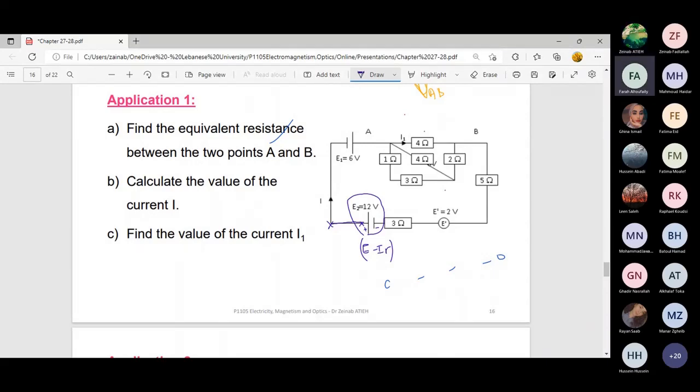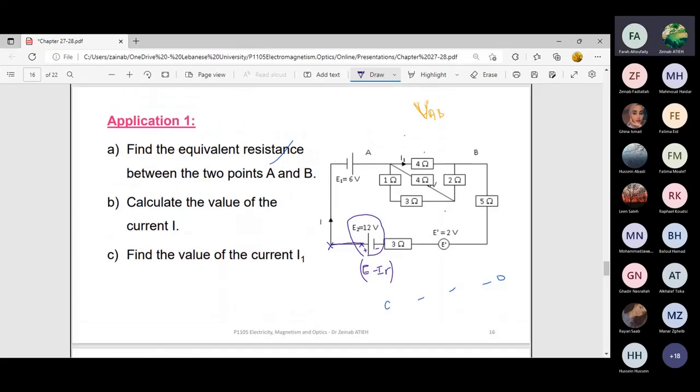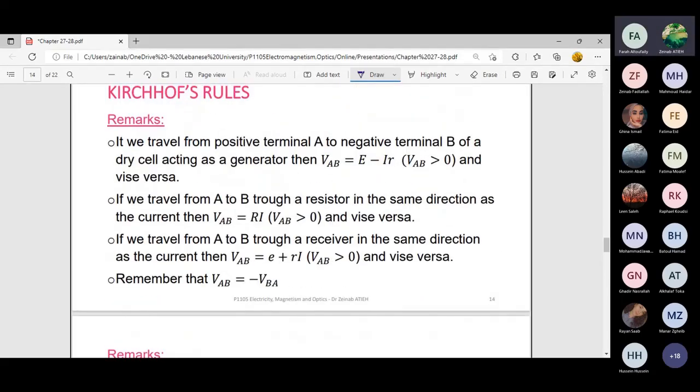You can repeat it, because the connection cut out. Okay, I will repeat. The first formula. You are moving on your wires in order to add all the voltages and sum them up to 0. You look at what is inside the wires or on the wires. If you encounter a generator, and you are moving from the positive terminal to the negative terminal of the generator, you place the formula E minus IR.